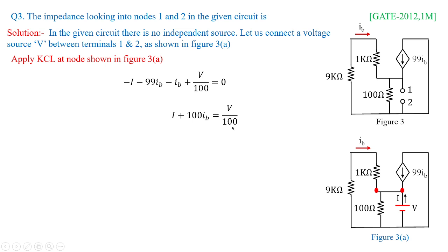Now just estimate what is the value of IB. After taking this equation as 1, what is IB? You will observe, it should be nothing but the parallel voltage V divided by the total resistance, and it is in opposition to this potential V. So IB will be equivalent to minus, because this is the upper plate and the current is shown coming towards it. So IB equal to minus V by 10K, you can represent as 10,000. So this is how the value of IB would be.